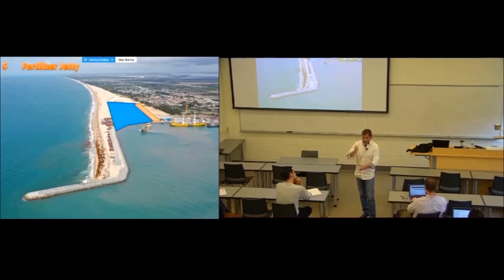Do you know how they hit the pile with the hammer? The wave equation, yeah. Yes, they use the wave equation to see if there are anomalies in the shape of the wave. I did the same with lateral, and we were able to predict the lateral capacity of the pile and predict the static capacity. But that's another section of the research.